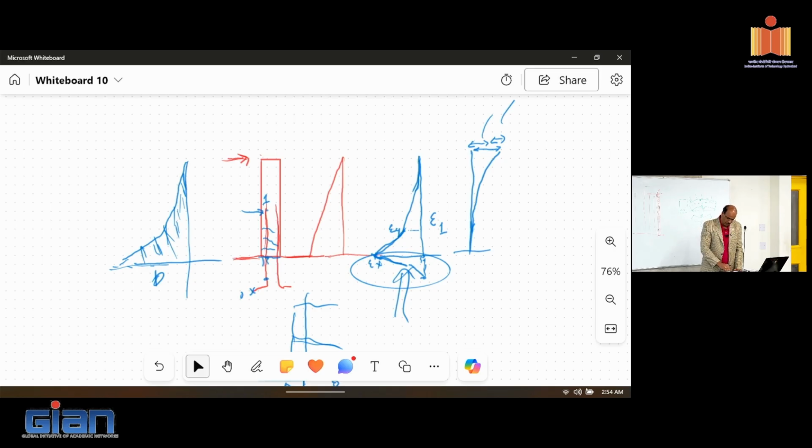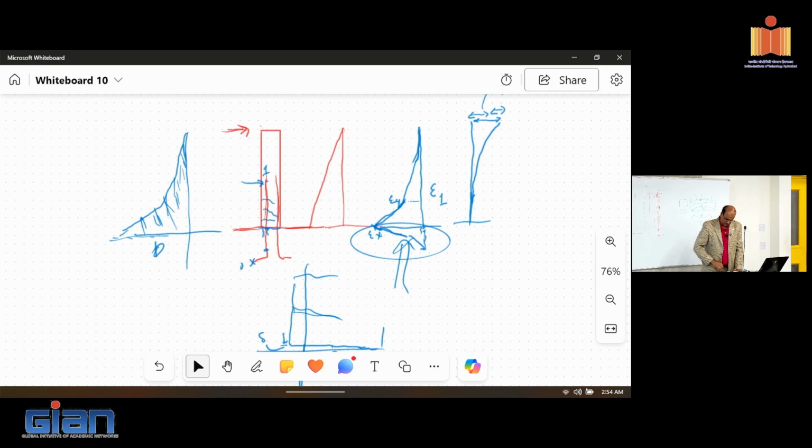Okay, so why I'm saying this is, I want to go one more step and say, if I look at force versus displacement, that's my force, this is my displacement here. It's going to remain elastic, and as yielding takes place and then continues to go plastic, this number will grow pretty significantly because in this phase, your penetration is going to be pretty significant. So the component will bring up more and more displacement.